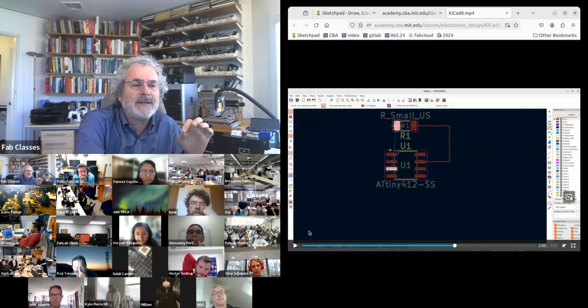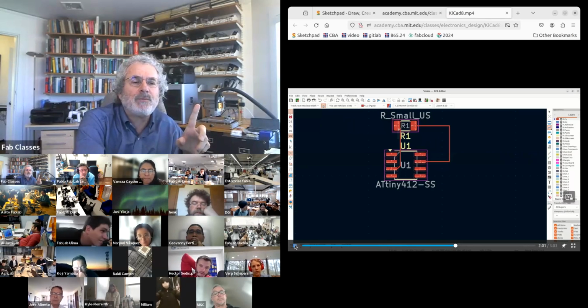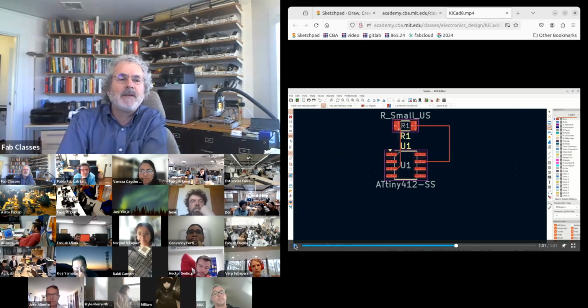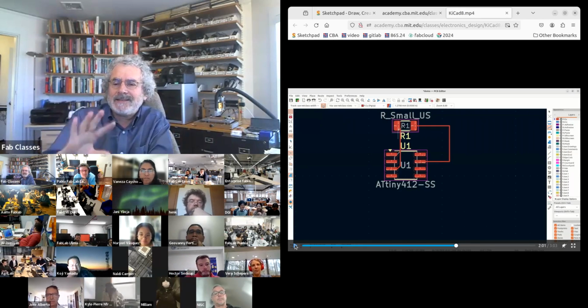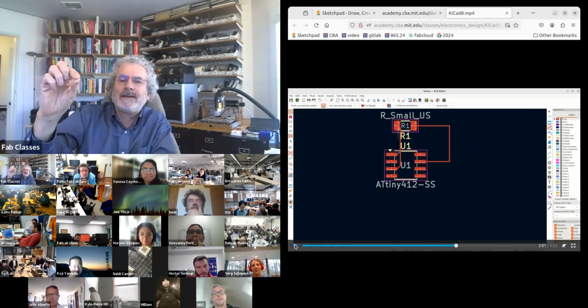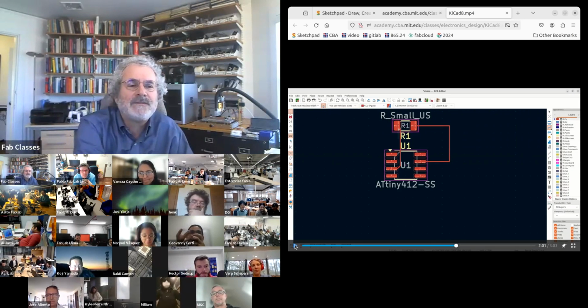And so I'm going to type the letter F. And as soon as I type it, boop, it just happened. As soon as I type it, it routed the trace for me. And it's interactive. You can start routing, and then you can tell it to finish.